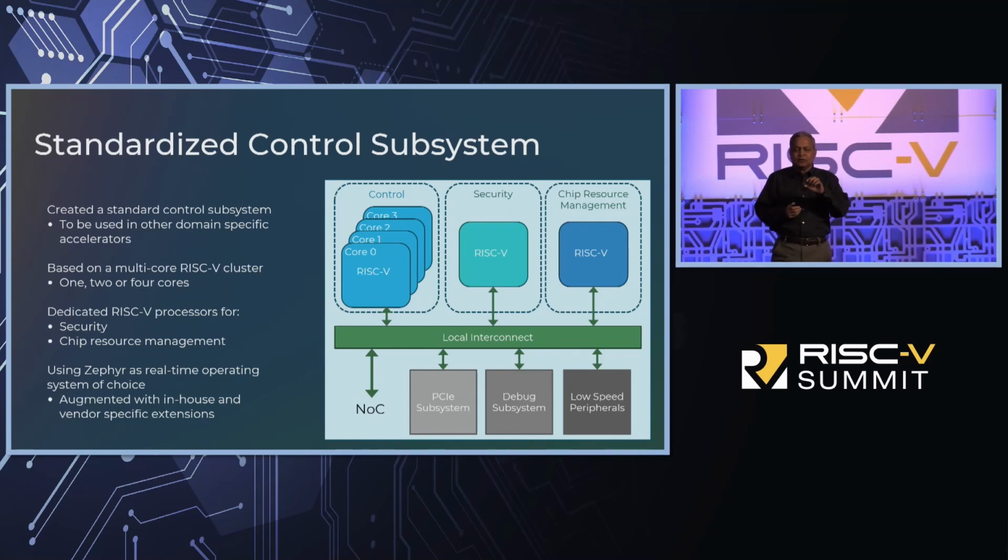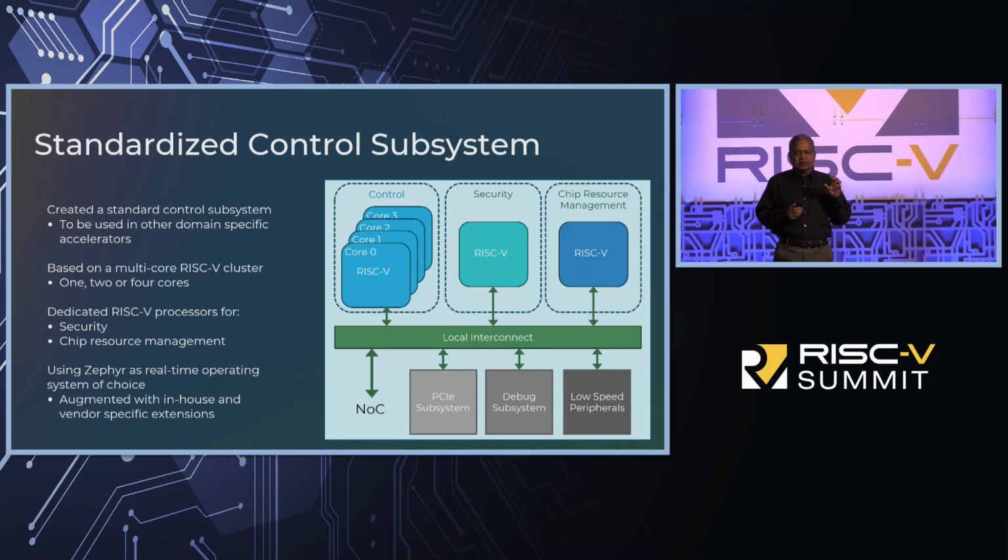Essentially we use RISC-V. So if you look at it, based on the multi-core RISC-V cluster, we created a control RISC-V subsystem. The second one is RISC-V specifically for security, and the third is chip resource management. So these are all the areas we covered, and we created a template. And then we will be extensively using this. And we have clearly adopted Zephyr as the real-time operating system of our choice, and we augmented it with in-house and vendor-specific extensions.